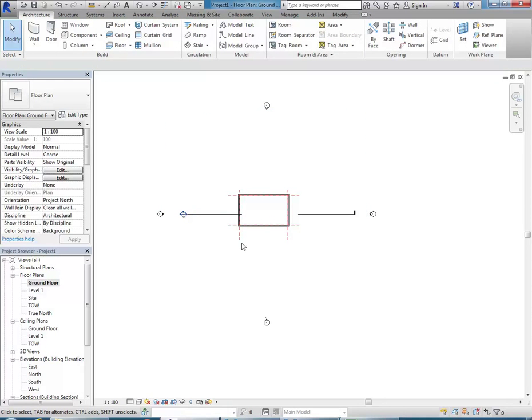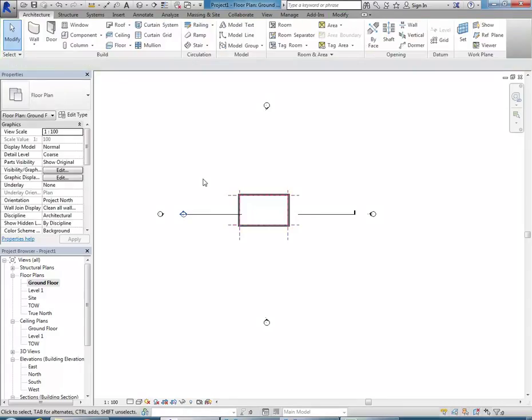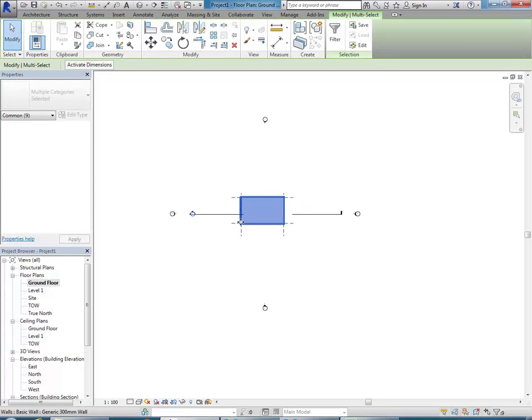And so if your building isn't centred inside those 4 elevation views, what you need to do is select the whole building, just make a window going left to right. At this point it's easier to move the building than to move the views. So again, left to right, we'll select the walls and also the reference planes if you go out far enough.